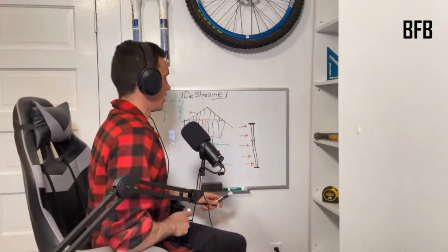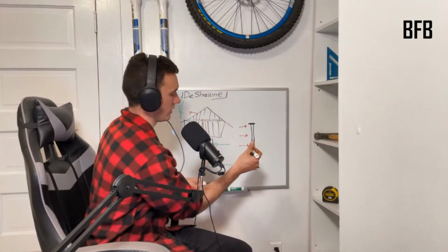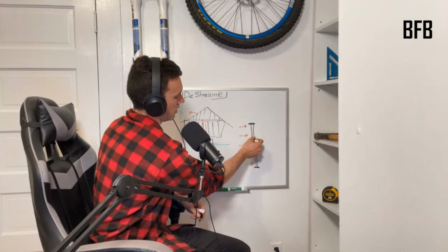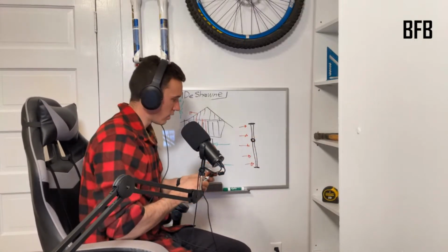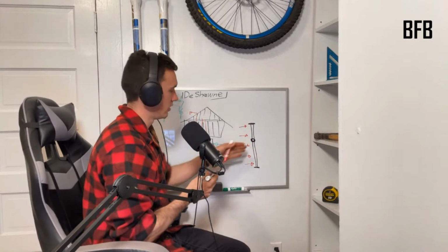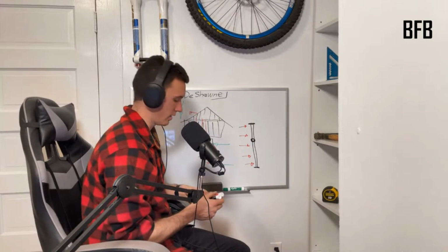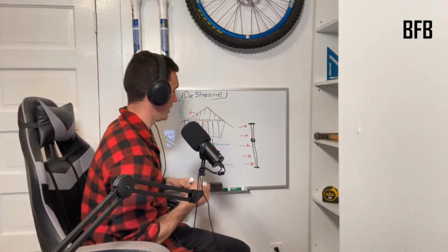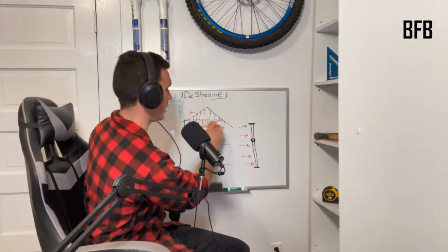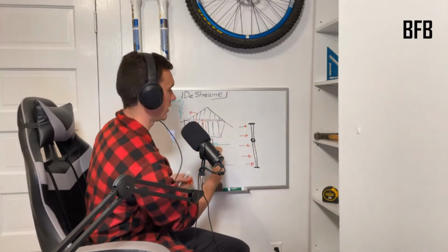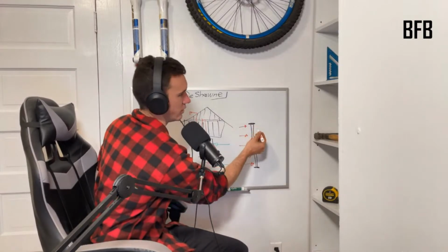Drop my marker. So what we have here is, if I draw this with a circle in the middle, you might think, well, that kind of looks like a hinge. That kind of looks like it might rotate about that point. Should nothing hold that there? So you would be correct. The problem that happens here is, worst case scenario, that gets blown really hard and there's nothing supporting that first ceiling joist, like a ceiling diaphragm, which there always is usually. Always usually. What a word.